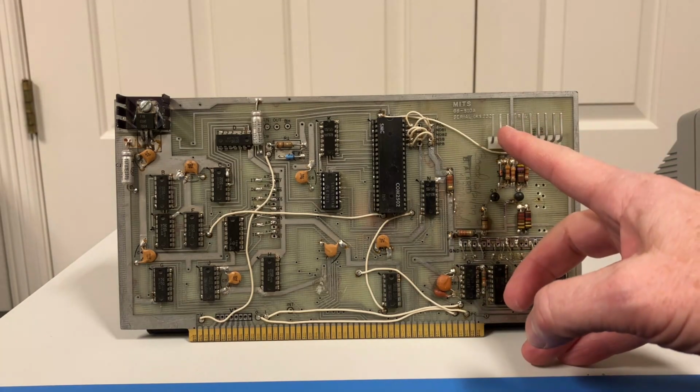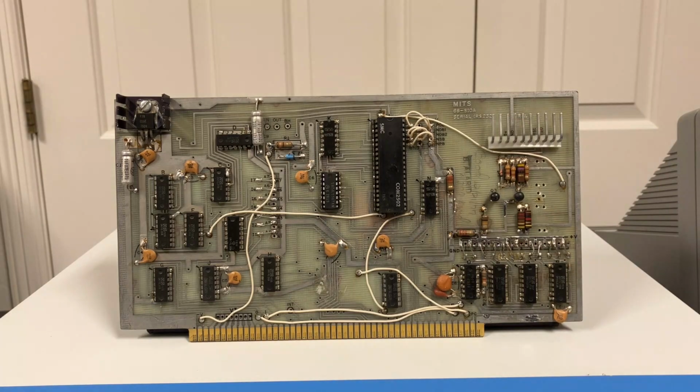This board also has 5 volts on this pin right here. And if you recall, I picked up that 5 volts on the IO4 board and put it on pin 18 of the DB25. That made it very easy to power that cassette interface without having to run a separate power wire to that. So in all these demonstrations, I'm going to get 5 volts hooked to that right wire in order to get it onto pin 18 on the DB9.